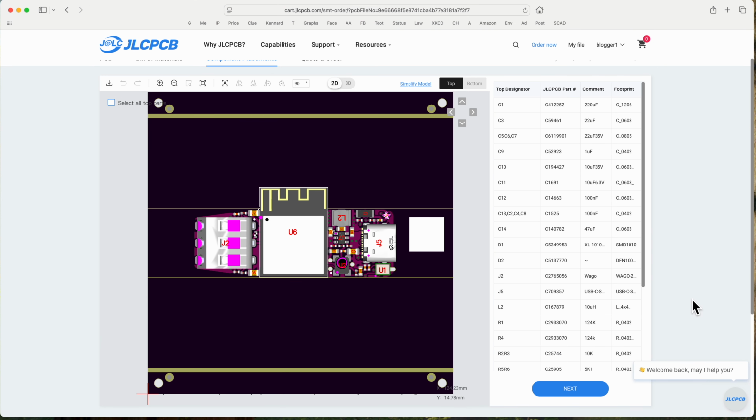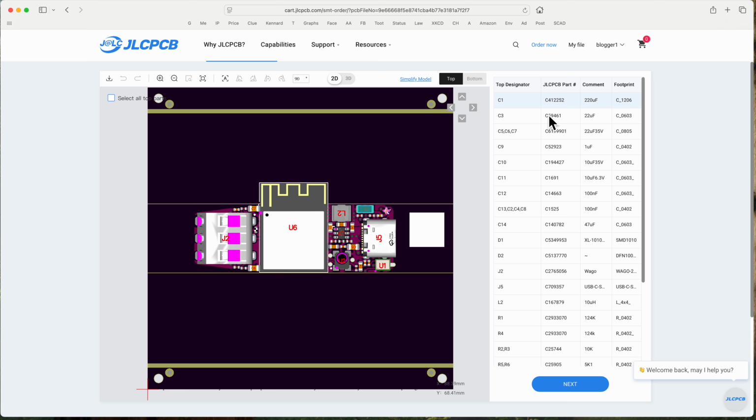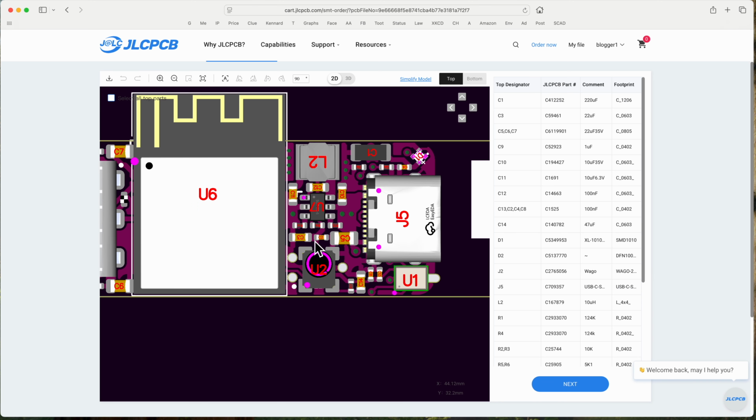And then this is the cool bit. That's my circuit board with all components. And I can go in and check they look right. So that's purple dots where pin 1 is, and I've got a mark there on my silk screen. Yes, that's pin 1. That's the right way round. Same with that dot on there. Same with that dot, and well, that has to be the right way around. It's particularly that dot and that dot there.